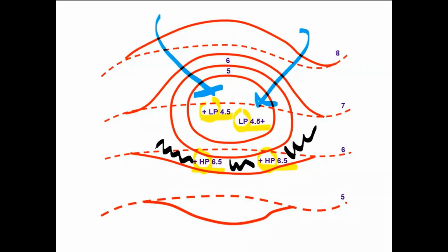And then the low points will determine the bottom of the system. You generally want to have more than one low point, so you spread the water out as much as possible. You'll also notice that the depth that we have for this system, because we've got a 4.5 and a 6.5, is about 2 feet, but we're going to make some adjustments to that in a minute.